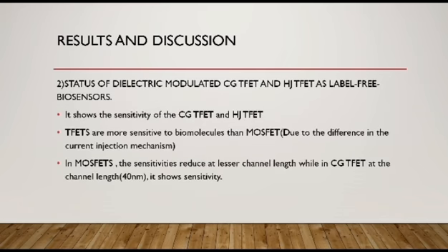Next, the status of dielectric modulated CG-TFET and HJ-TFET as label-free biosensors. It shows the sensitivity of CG-TFET and HJ-TFET. There are a number of important simulation and modulation works reported on dielectric modulated TFETs and FETs.